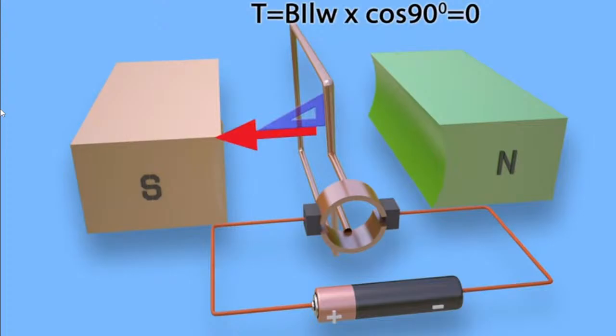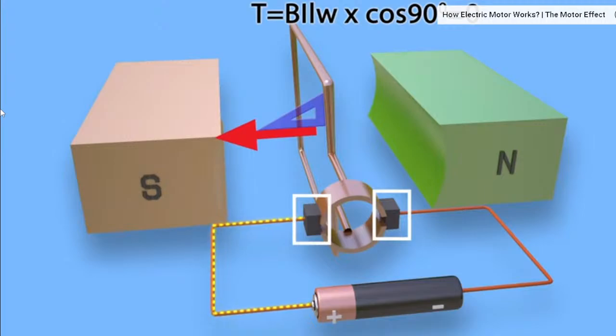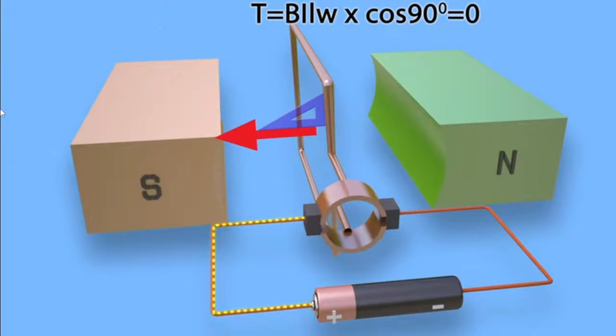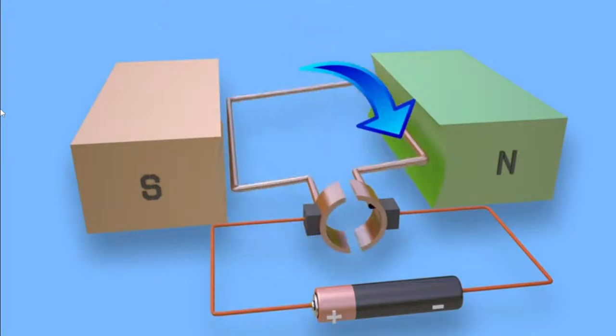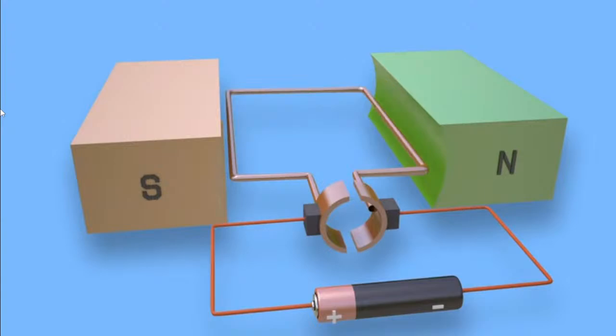After rotation, the turn comes to a vertical position with respect to the magnetic field. At this position there is no current in the conductor because the turn, conductor and brushes rest between two commutators. Hence, there is no force acting on the conductor, but due to moment of inertia, the turn continues to rotate and comes horizontal again. The position of the conductors has changed here. That means the conductor which was previously in the left position comes to the right position, and the one which was previously in the right position comes to the left position.